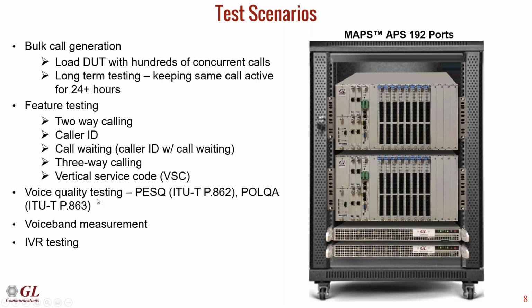One thing we're definitely going to talk about is voice quality testing. Like I mentioned, we can send and receive predefined audio files. Because you can send and receive audio files, you can measure the subsequent voice quality on those files. We support the popular industry standard algorithms such as PESQ and POLQA to give you a true objective mean opinion score of the voice quality. That's a really powerful capability that we offer. And for all of the different phone calls, you can get different voice quality scores.